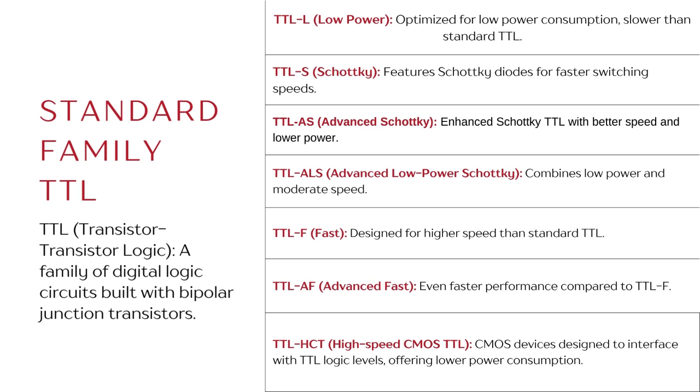TTL, or transistor-transistor logic, is a widely used digital logic family based on bipolar transistors. TTL-L, or low-power TTL, focuses on reducing power consumption, but has lower performance. TTL-S uses Schottky diodes, which allow faster switching speed compared to the standard TTL. TTL-AS, or Advanced Schottky, improves speed and reduces power compared to the previous versions.